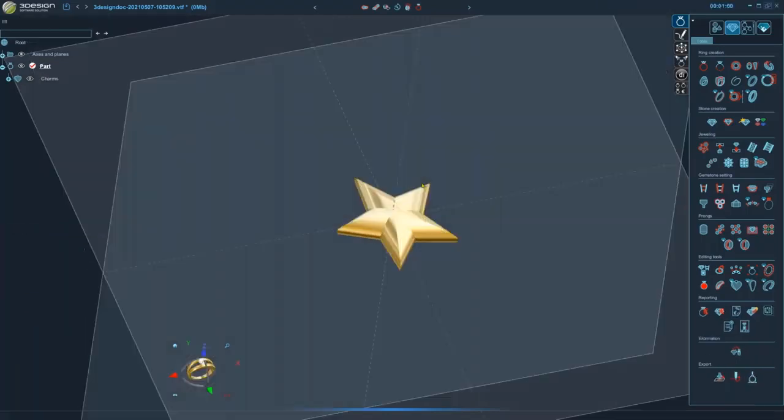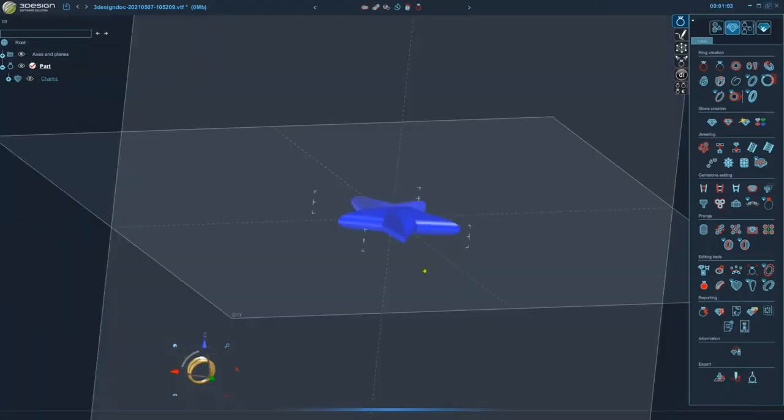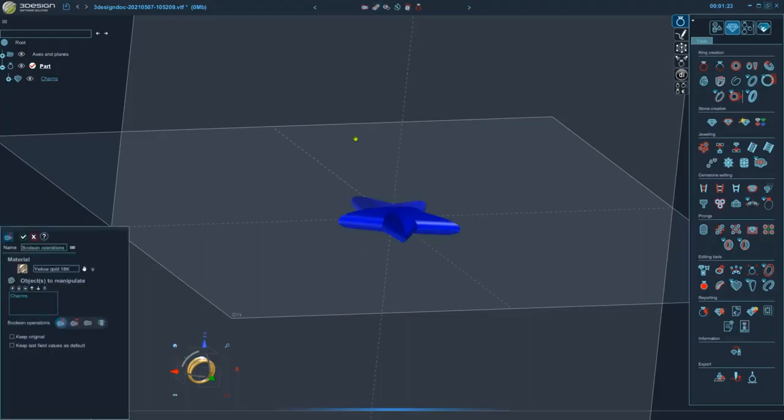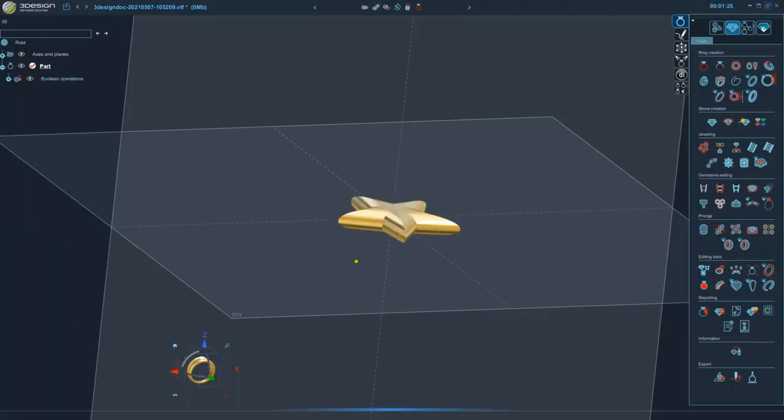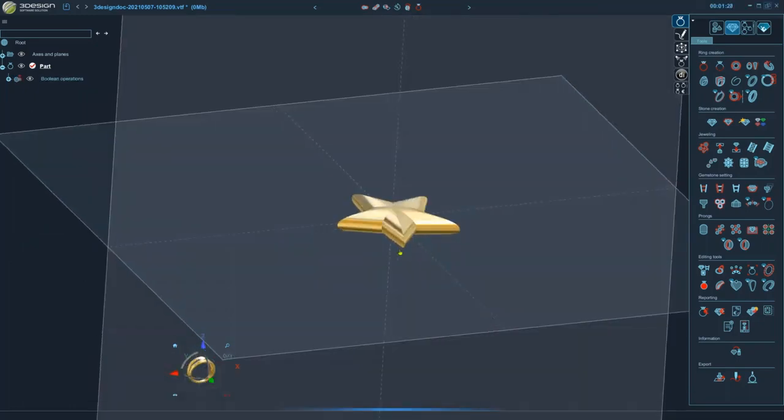And then when you validate these, you'll notice it is a group. So it is just two pieces that are mirrored. You will have to Boolean them if you want it to be solid. But I think we left that as two pieces in case you wanted to go ahead and ungroup them and maybe cut out some of the inside or do something else to them if you're doing locket style charms or something. But by default, they do need to be Boolean together. And I did want to show you if I'm doing this from a custom object, what'll happen sometimes.